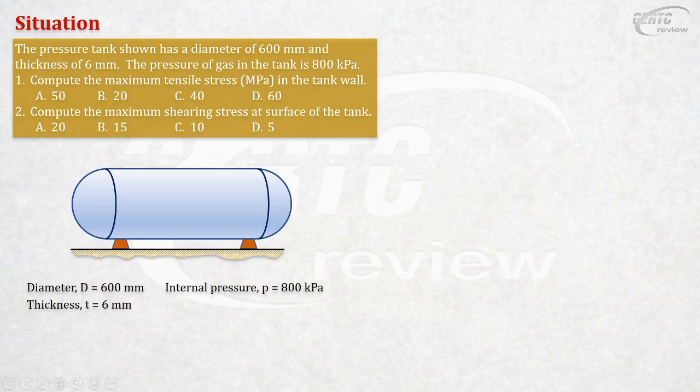Well, I'm just explaining to you the basic because kung malaki yung diferensya ng sagot, then it should not be a thin-walled pressure vessel anymore. But the examiner, I noticed, if he emphasizes the outer and inner diameters, then use the inner diameter. I hope you get my point.